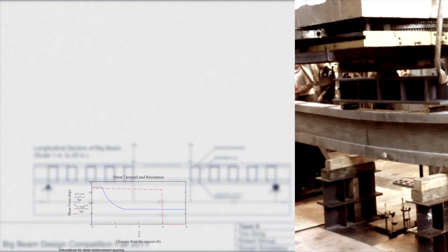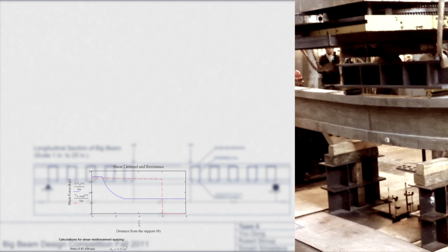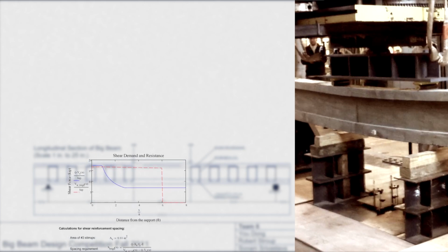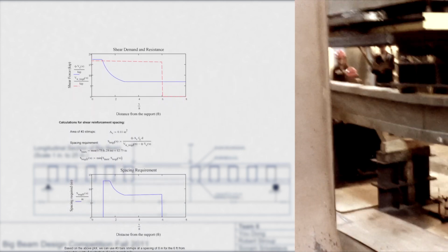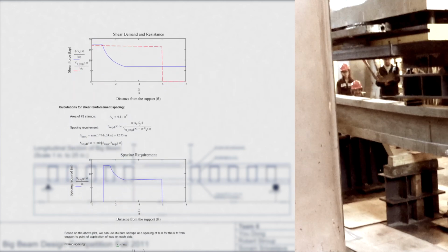Using this found value of 263.8 KSI, we then calculated the nominal moment capacity at 104.66 kip feet. Using this nominal moment, we then determined the corresponding factored live load occurring throughout the beam. Because this live load was greater than the 32 kips of force and less than the 39 kips of force specified, our design section was okay, per the specified rules of the contest.